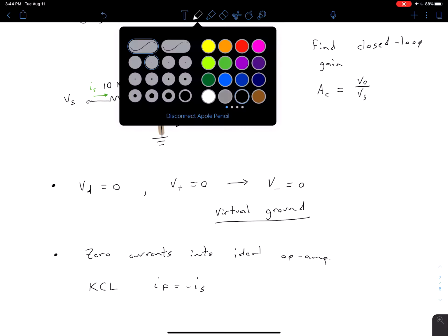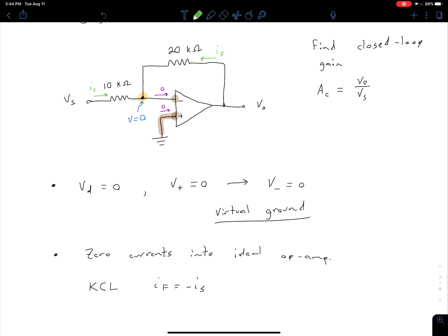Well, to make it a little easier to see, I can explicitly define these voltages. Of course, it's implied that this Vs is relative to ground. Well, since this point here is at 0 potential, then we could write explicitly with polarities our Vs like such. Same thing with our output voltage. Because this output voltage is implicitly related to ground, we can write that it's positive here and negative over here, which is ground, or a virtual ground at the very least.